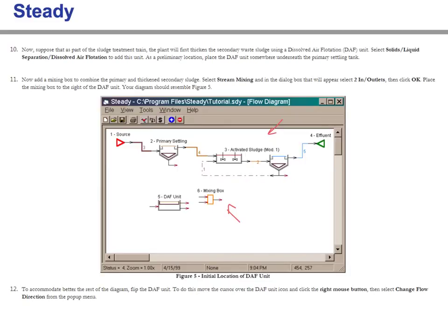So in this example, we consider not only the water but also the sludge treatment, so this DAF thickening was considered because it allows the concentration of the solid materials from the sludge to reduce the water content, so that later we can treat this easily.